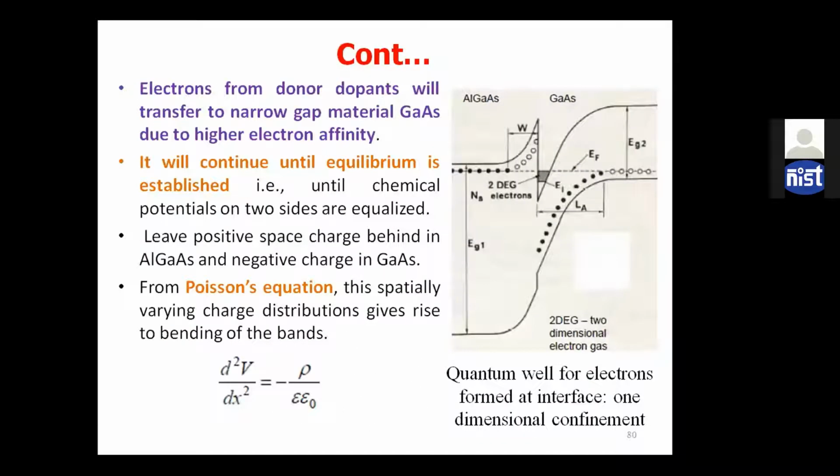So why does this band bending occur, as I explained? The band bending energy you can get from the kinetic energy plus the electrostatic potential energy. But that kinetic energy is fixed, and depends upon the band structure. The electrostatic potential you can get by solving Poisson's equation, which depends upon rho.